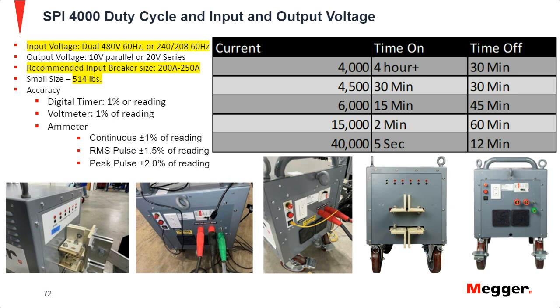Our next question, and forgive me if I butcher it a little bit, but they ask: David, I have a 2000 amp rated breaker with a 1200 amp trip setting. If the long time test is three times that, 1200 amps times 3 is 3600 amps. Is that harmful to the breaker? I understand that it's for a short period of time.